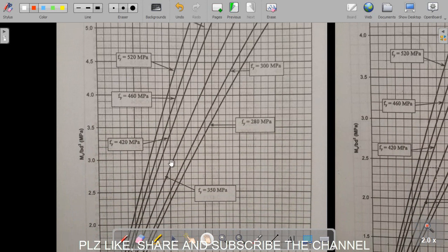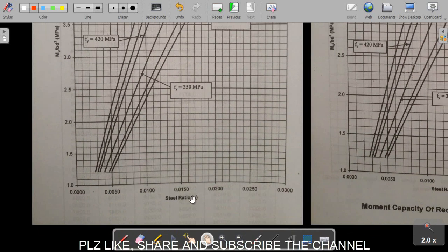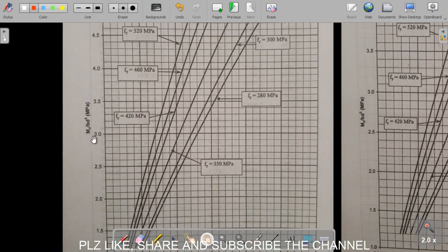This graph is drawn for Mu by BD square and rho. So we will calculate Mu by BD square, and let's say it comes out to be 3. By extending that point towards your desired steel, let's say the steel is 60 KSI steel, this is the point for 420 MPa.